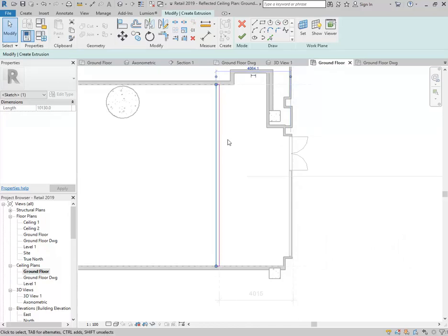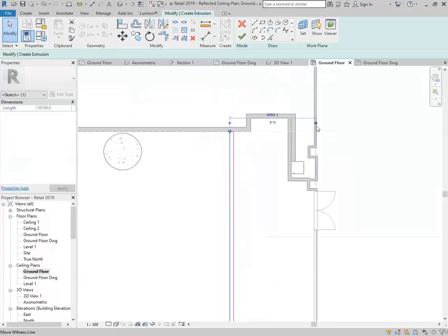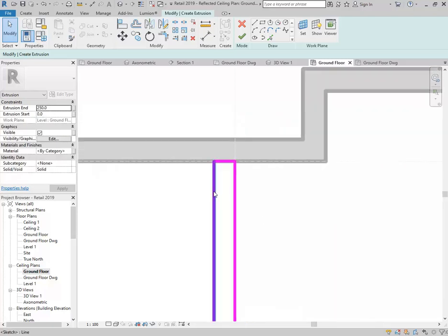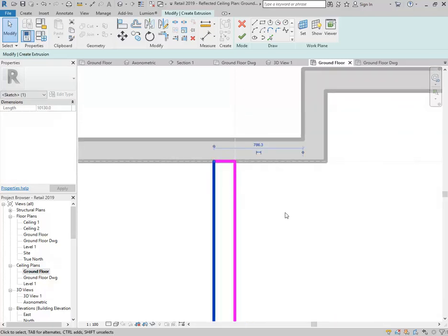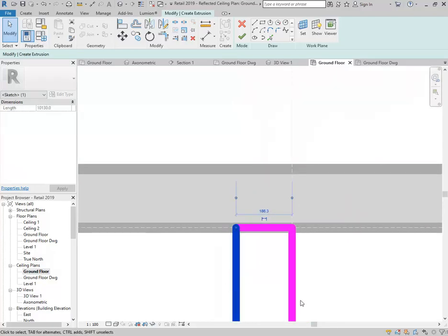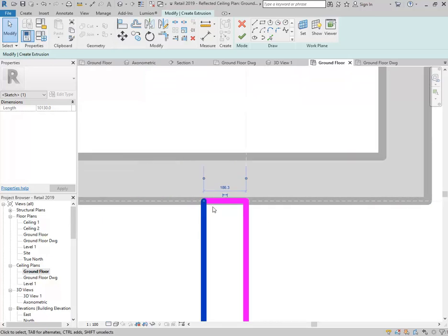It's annoying, it's going to the wrong thing, so I'll show you a good trick. If you find the dimensions come up going to something you don't want, I want it to go to here. Good trick there, just zoom in. And you'll see then it should pick up the smaller thing, so I'll zoom in a bit more. And there we are, so now it's dimensioning to here. Now you can drag that, you can always change where it's measuring by dragging that marker as well, but that zooming can help.